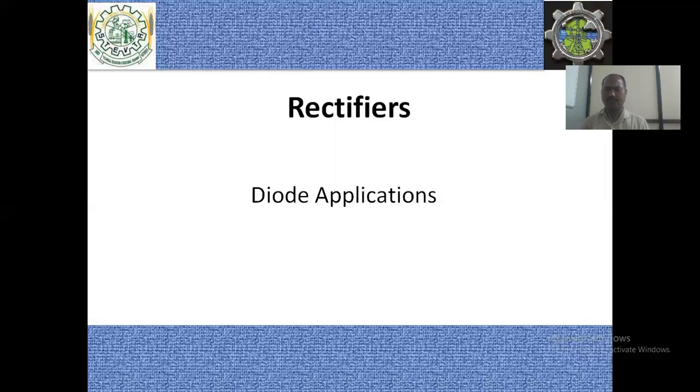Different things are used for removing that pulsating component, namely the filter and the regulator. According to your need, you use the particular configuration, a filter or a regulator. But in a normal application, such as a small kids' vehicle or other small kids' devices, the half wave type of rectifier is used, because they don't need an actually regulated output.